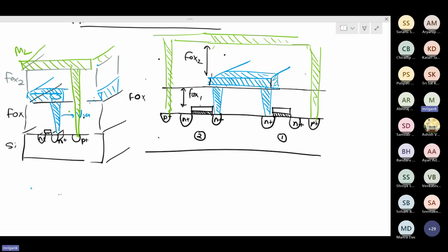In the physical design, we actually make use of these layers. So they are called layout tools. In the layout tool, we make use of these layers, M1, M2, polysilicon, your oxide, all these different layers to actually create the transistors at different locations and also make the connections using metal 1, metal 2 with appropriate dimensions, appropriate interconnects, etc. So this part you should be aware of.